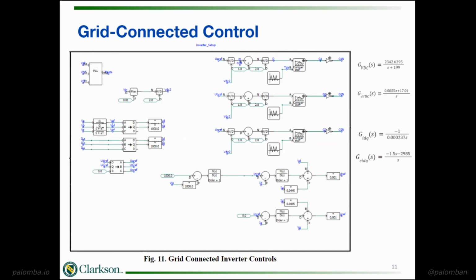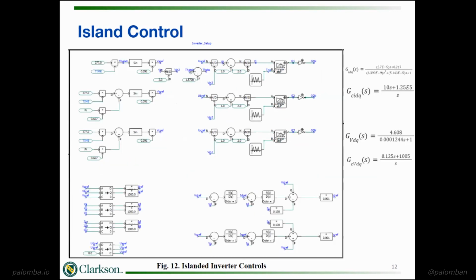And on the next slide, here we have what we modeled in PSCAD for the grid connected version of the control for the inverter, which is rectifier control. And we have the controller for both the voltage loop and the current loop on the right there. And here we have how we modeled it for island control with the transfer functions on the right for the associated system.